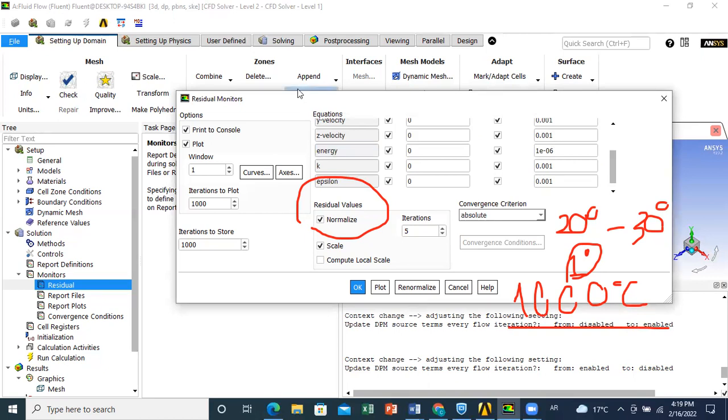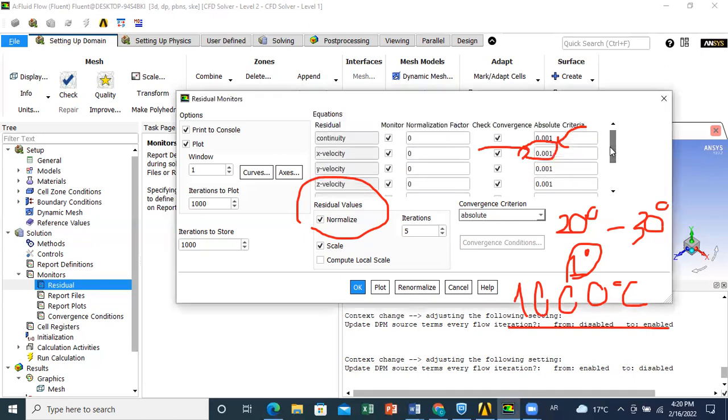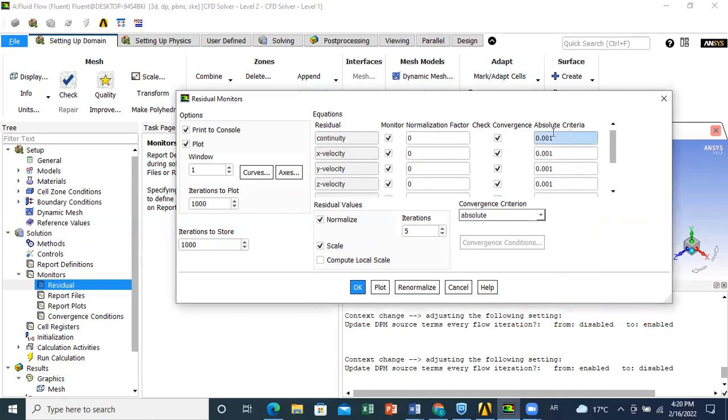As you can see, by default, the energy in ANSYS is characterized directly by a more constrained residual, 10^-6. Why? Because, as I told you, energy is the easiest one to converge. So 10^-3 will be reached in a very fast way. So to have more accuracy, we go up to 10^-6 for energy. For other variables, you can change the residuals depending on your applications. Higher accuracy needed will require smaller residuals. So you can set, for example, all your residuals to 10^-5, 10^-6.